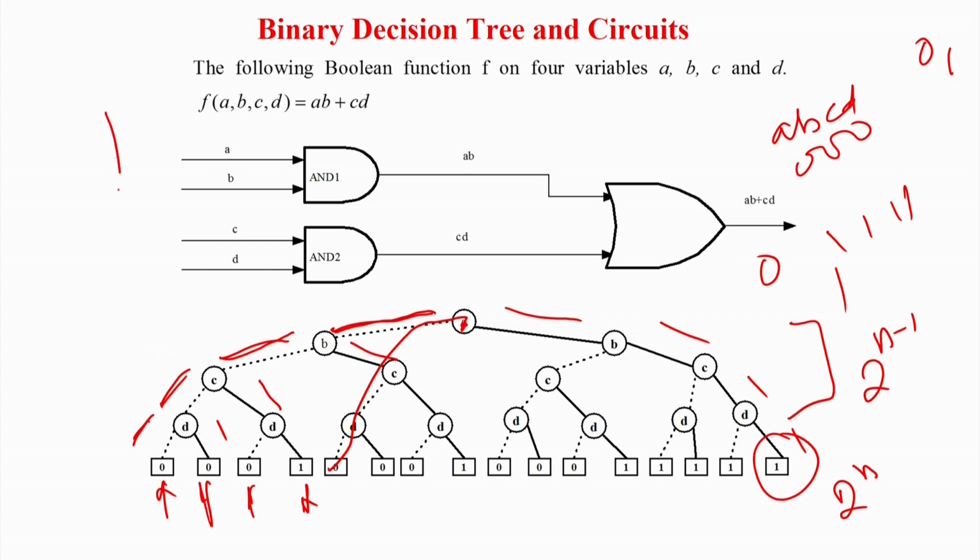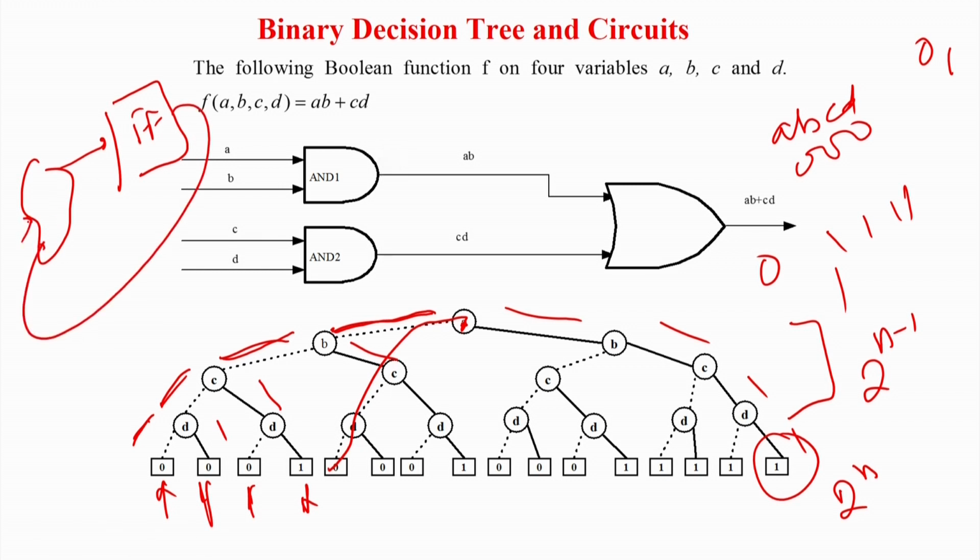If you take something like this, it is basically your flip flops, the register bank, then you have an input. This is your combinational cloud, that is your next state logic block, and there are feedbacks from here, and also there are primary inputs. So this is nothing but your combinational circuit. If you have some good data structures to model this combinational cloud, modeling the flip flops is nothing but just enumerating the state values.